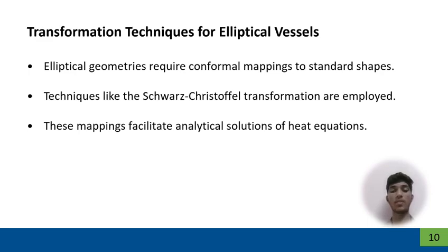Transformation techniques for elliptical vessels. Elliptical geometries require conformal mapping to standard shapes. Techniques like the Schwarz-Christoffel transformation are employed. These mappings facilitate analytical solutions of heat equations.